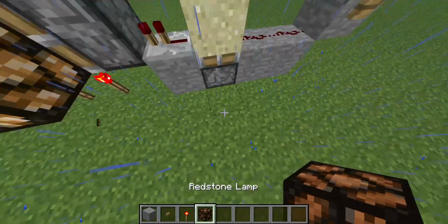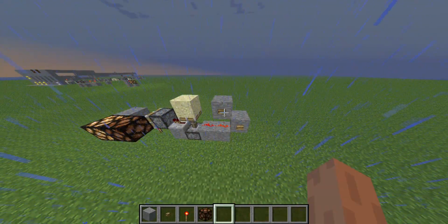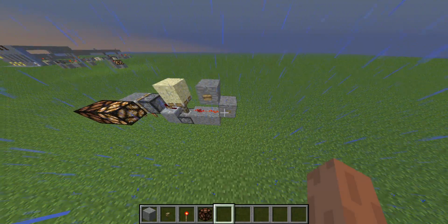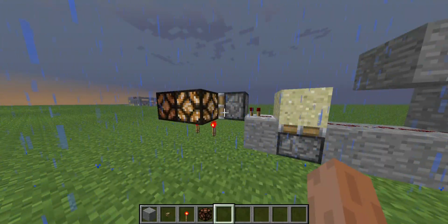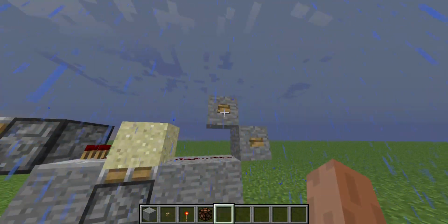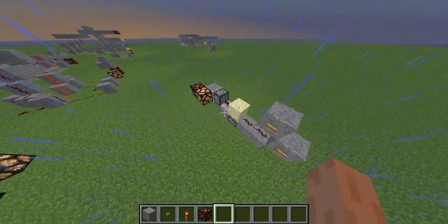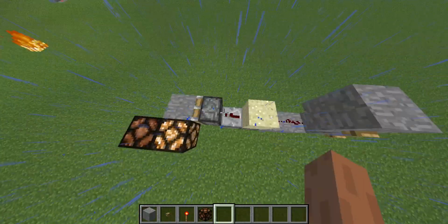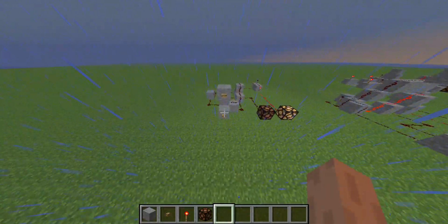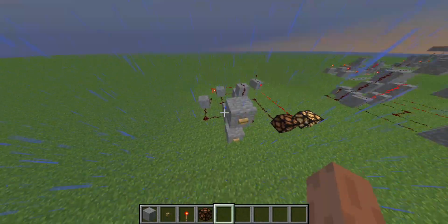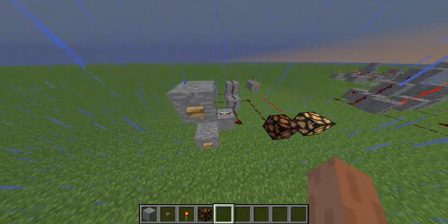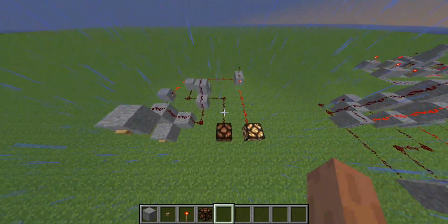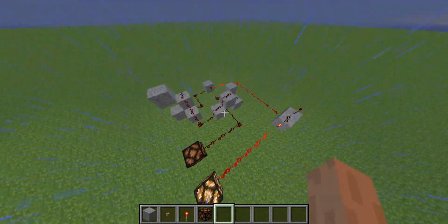So, well, what if I add another torch so that when I press this, it swaps which one is which? Again, not an SR latch. This is not an SR latch. These are hooked up to the same point to toggle the same thing. An SR latch always has two different buttons controlling two separate parts of the circuit that turn on two separate parts of an output.